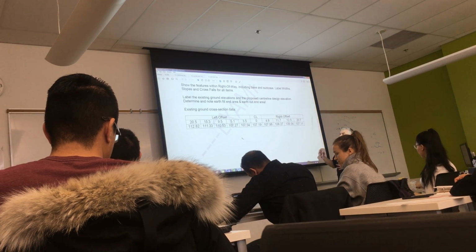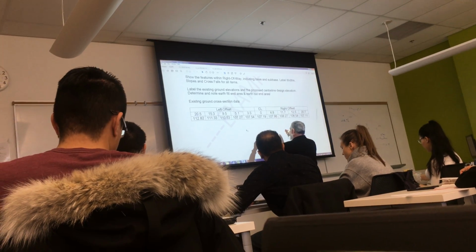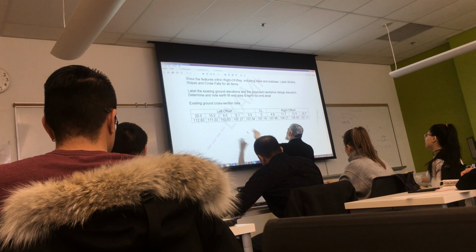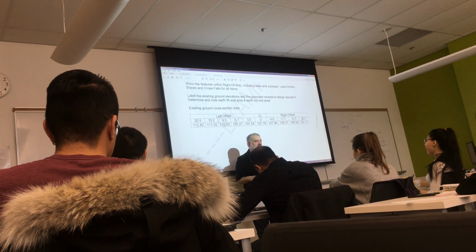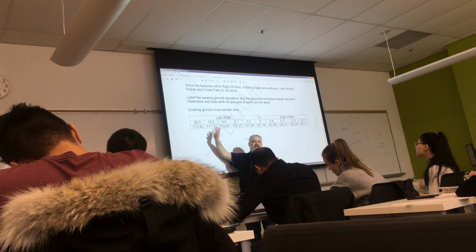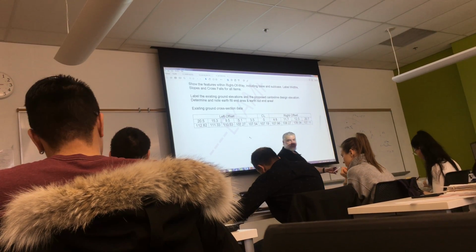The other thing you need to be mindful of is left and right. If 0 is in the middle, left, if we're looking into the board, right? If we're looking up chainage, the left side is your left hand, the right side is your right hand. Left is sometimes called negative. So if it doesn't say left, you might see negative. So this is the coordinate negative 20.5, 112.82. All the elevations are positive. Offsets are either plus or minus, right or left.